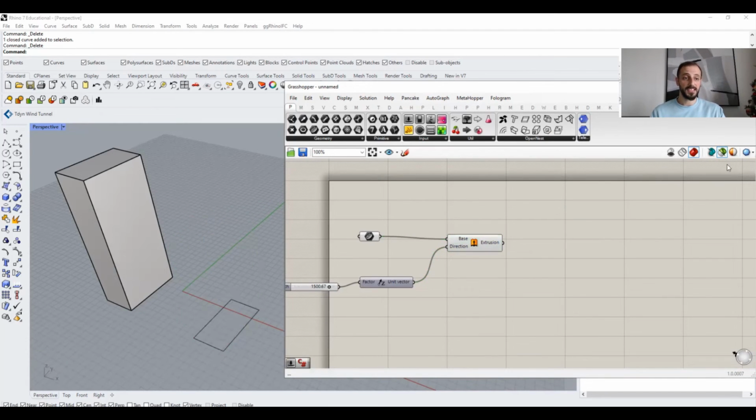So if I turn this on and select this, it will show me only the selected components and the geometries inside of those. Obviously these are still valid. If I select this, I don't see anything. If I select this, I see things only when they are selected, as in wireframe. And if I select this, I see things in shaded.